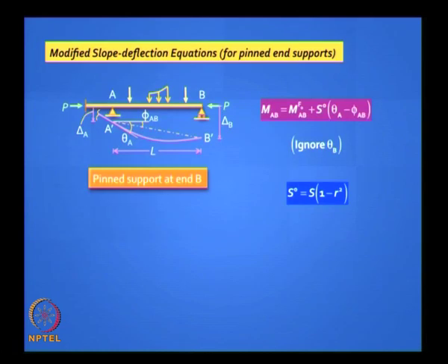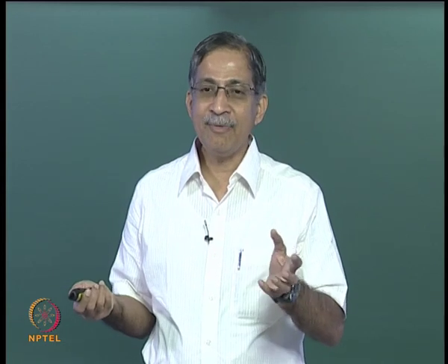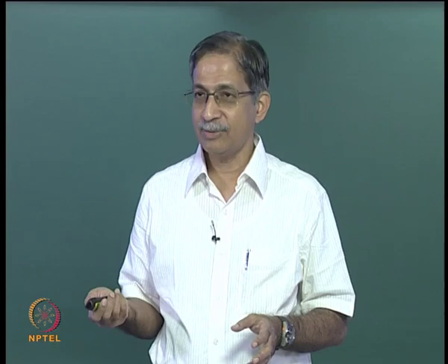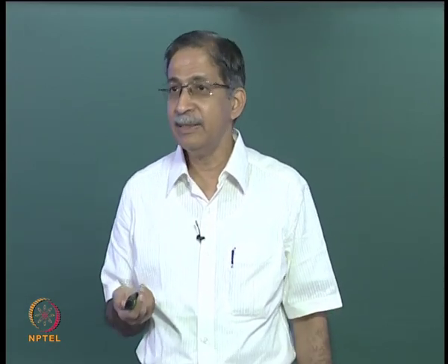All this we know. Now when we did the slope deflection method, we took advantage of situations where the far end is hinged or pinned, is it not? Because what is the advantage of doing that? Equation to find the number of variables. Not variables, what is the right terminology? The degree of kinematic indeterminacy reduces, right? So we can take the same advantage here.